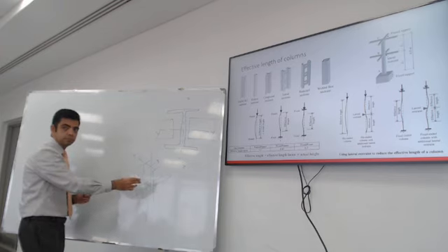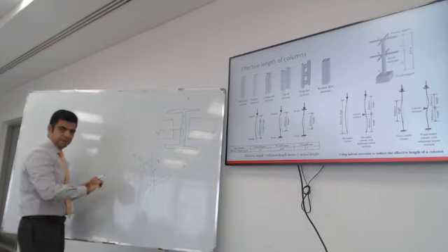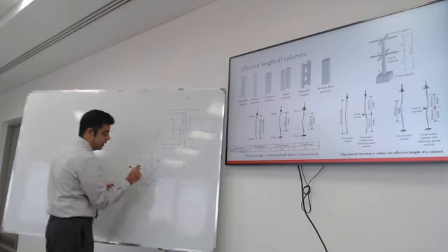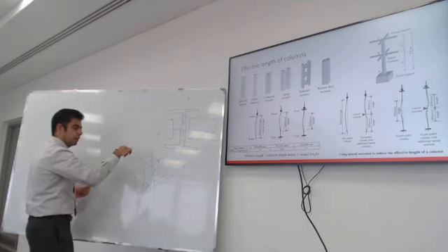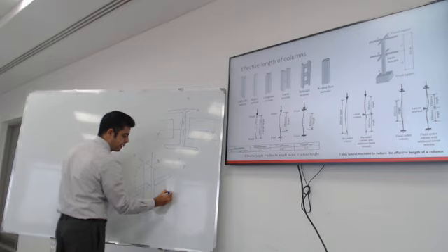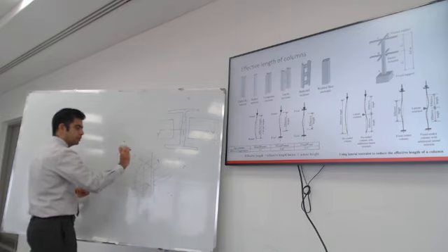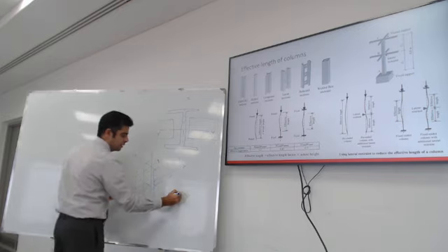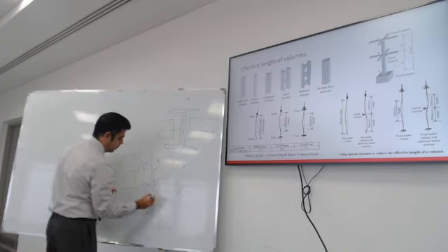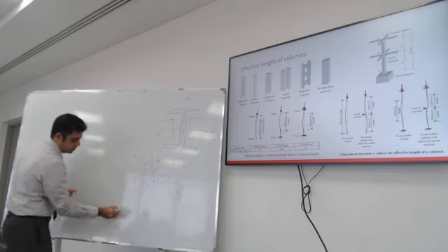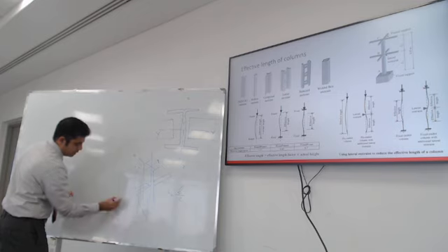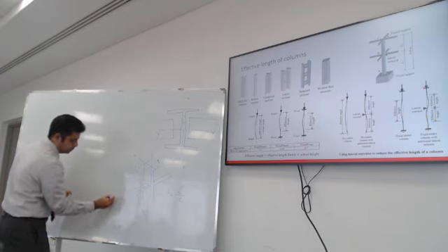is from the bottom till the top. So let me say this. In this case, the buckling about Z, the effective length about Z, is the actual length divided by 2, at the half, at the center. L divided by 2.